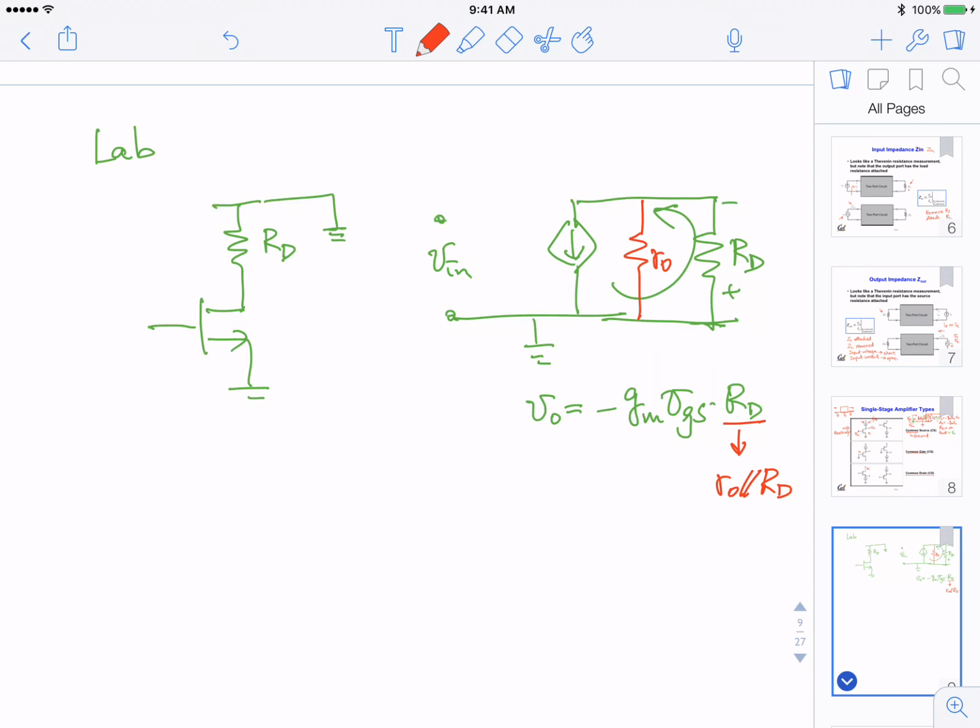So are we always considering RO is a very big number? Yes. Typically we will show more examples later. It's useful to have some order of magnitude for these typical transistors. Of course, this depends on the technology you use and the size of the transistor, so it is not a constant value. But if you are analyzing a circuit and wondering which term is big and which is small, think they are roughly about 200 kilo ohm.